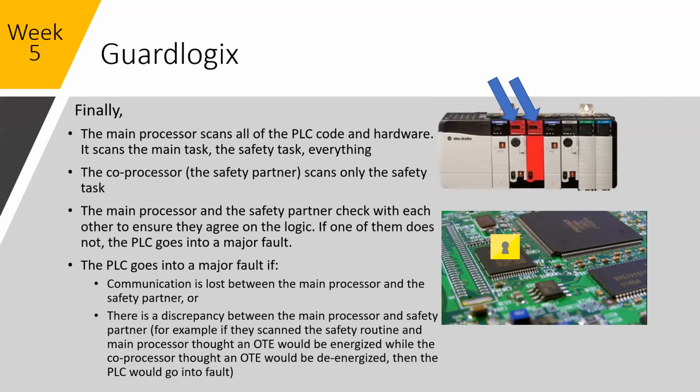The other thing to be aware of is if you see a safety processor and you do not have the logic for it, there's a very good chance you won't be able to upload it. So the safety stuff will typically have additional security, and then they will cross-check.